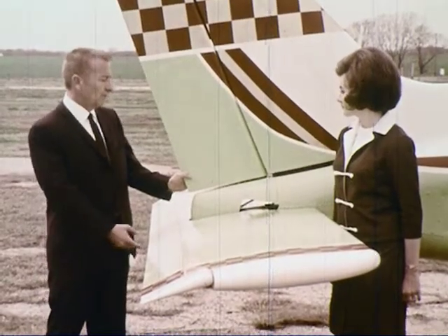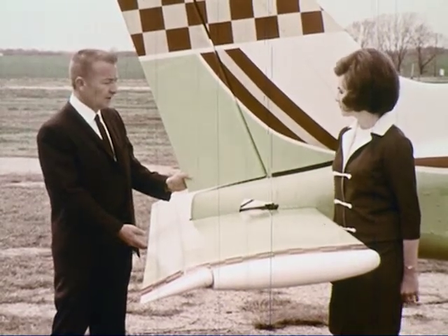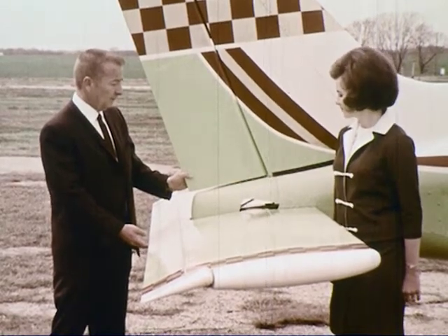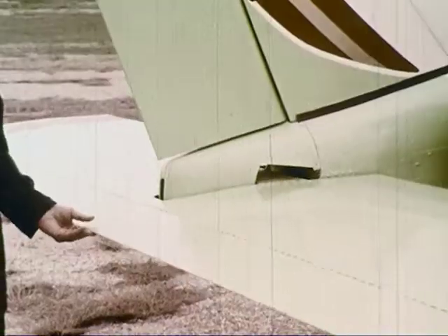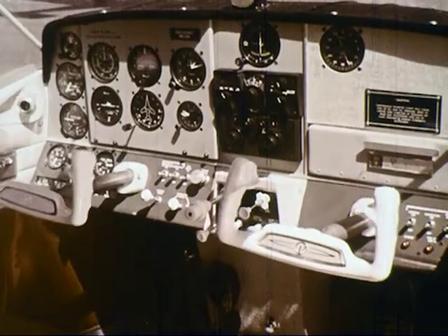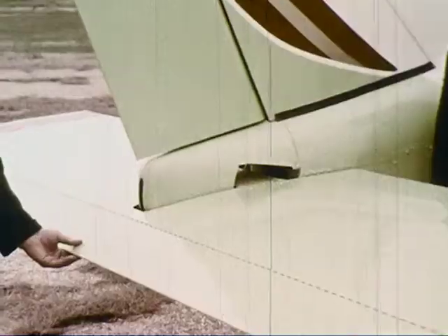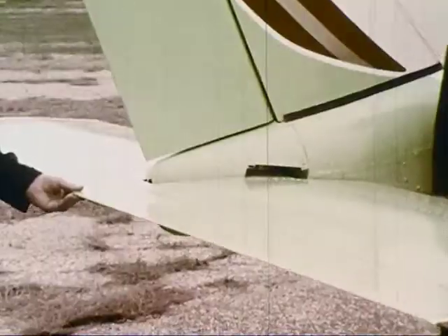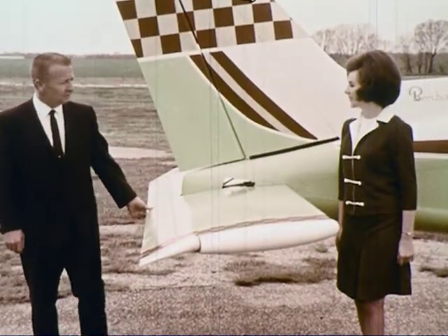This is the other control surface located at the tail of the airplane. It's called the stabilator. Its movement is controlled by the wheel in the cabin. If you move the control wheel back, this moves the stabilator up, causing the nose of the airplane to pitch up. If the wheel is moved forward, the stabilator is moved down and causes the nose of the airplane to pitch down. That is really interesting. Now let's get in the airplane and look at the instruments. Okay.